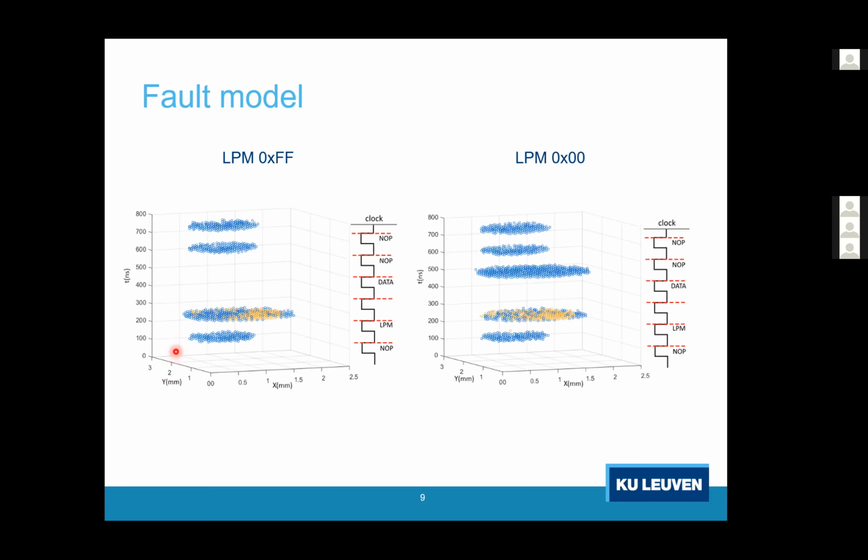So the blanks in between these clusters are not due to us choosing an interval which was exactly the clock period, but just because we were not able to inject any faults in between the clock edges, because we were using such a small pulse to inject the faults.